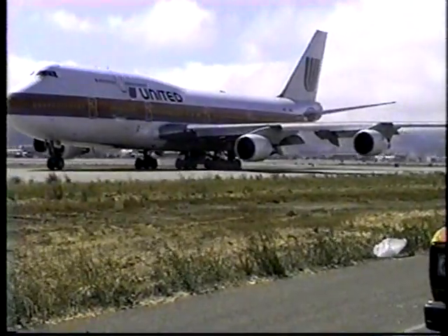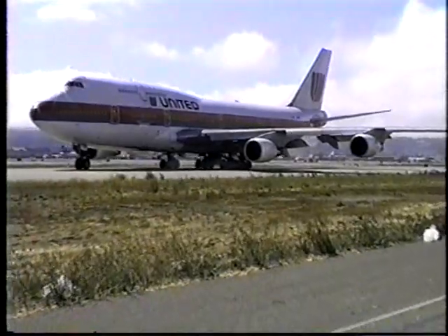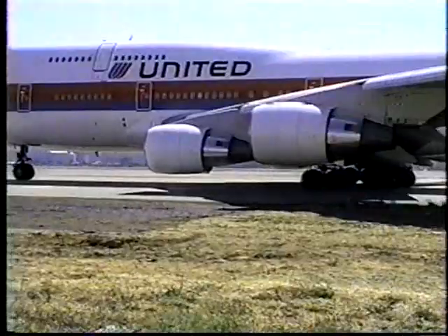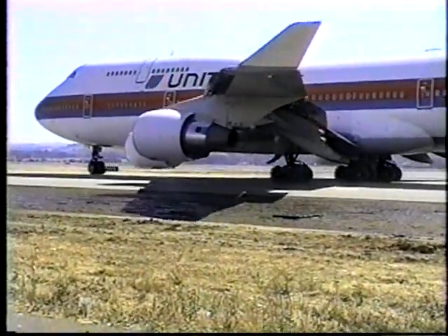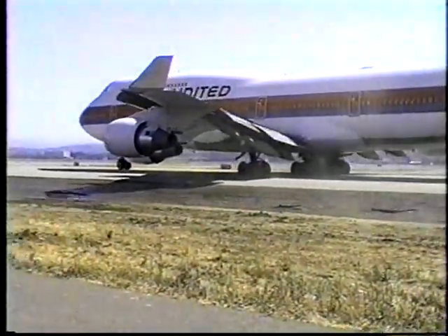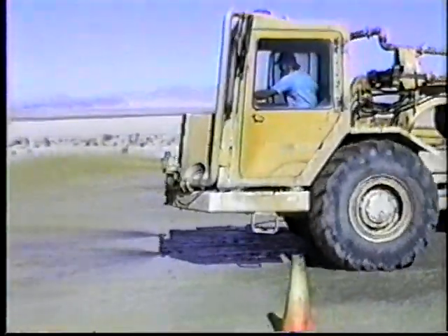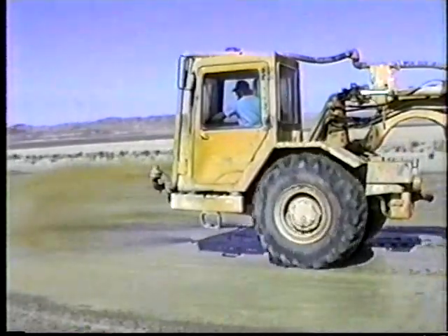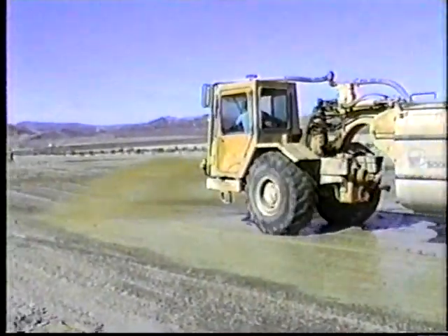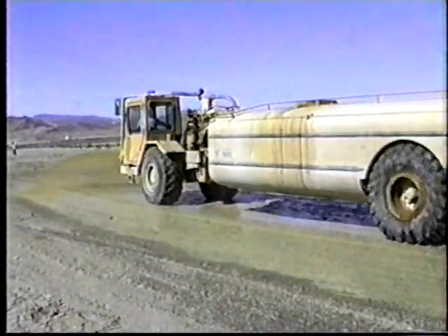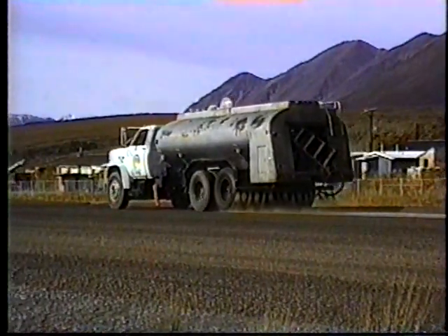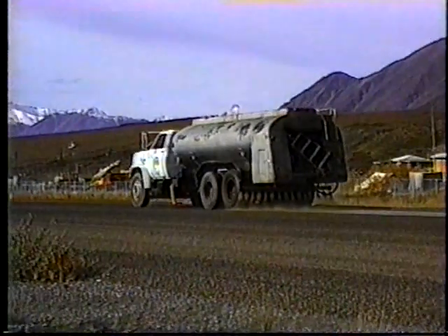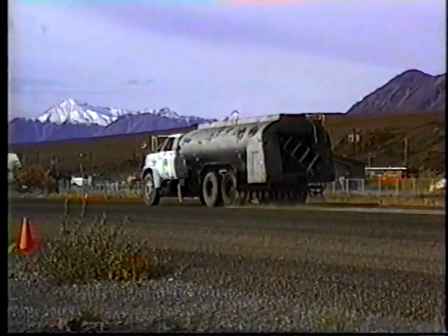This runway shoulder treatment has been applied to prevent dusting and foreign object damage to aircraft. The road oil treatment remains undisturbed by jet blast, even though it's being tested here during the earliest stage of curing. While bituminous distributor or spreader trucks are the preferred equipment for normal surface spray applications, pressurized water trucks are often used for smaller projects, such as this surface penetration for helipad dust control, or for projects at remote locations, such as this surface seal being applied to a stabilized aggregate at a remote runway.